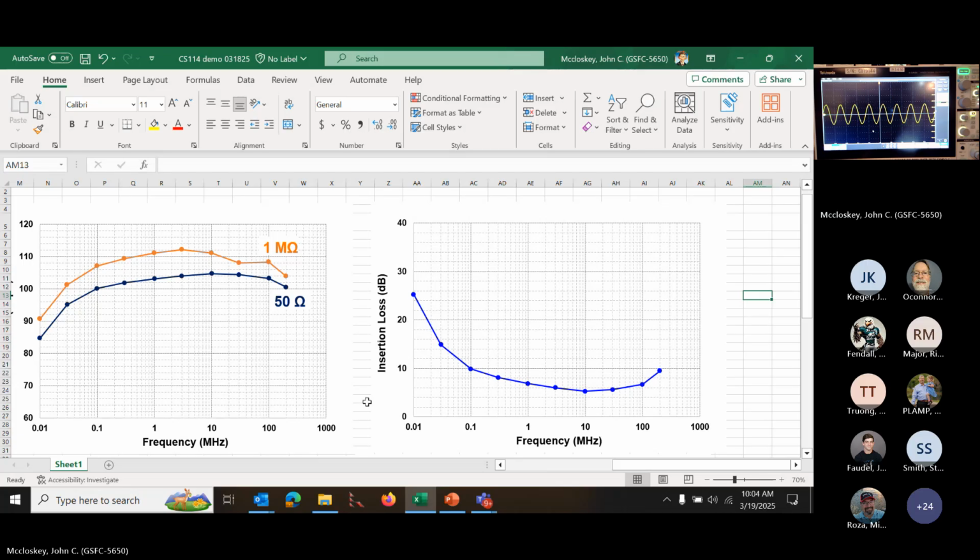So this establishes your open circuit potential, at least up to 10 megahertz or so. I don't necessarily trust these levels as much up here, but in the worst case, you basically could say that this line more or less extends here, that you're going to be about 10 dB higher than these injected levels. So now we want to see, what do we get into a short circuit?